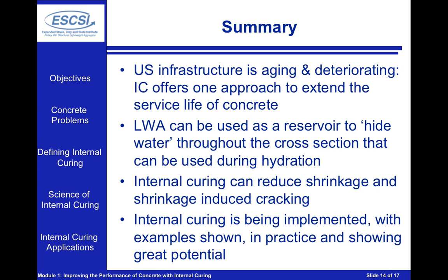The one thing we do need to be aware of is we do need to do quality control testing on our lightweight aggregate to make sure that we understand our moisture content. But once we've done that, and once we've done our proper adjustments for our moisture content, this really looks and places like a conventional concrete.